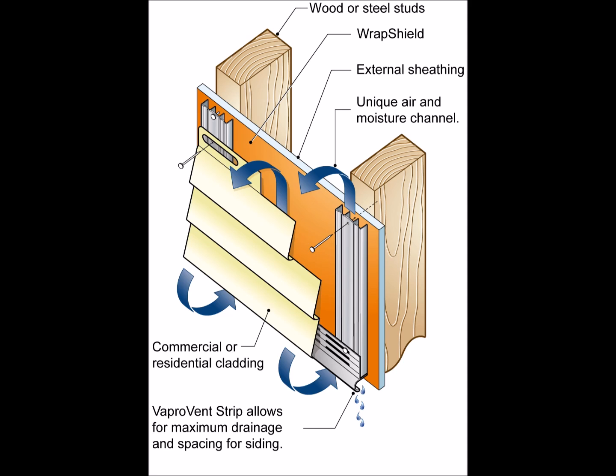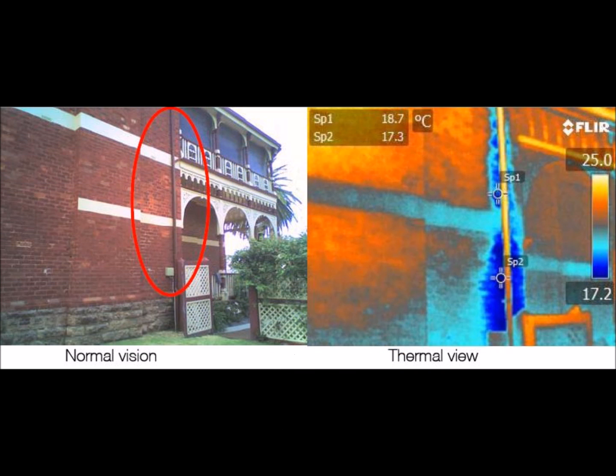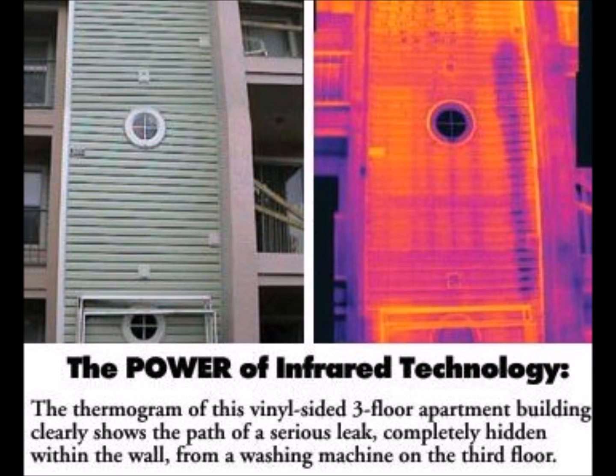You should know that if you're using a thermal imaging camera and there's spalling taking place, there could be a temperature difference in that area. It is most likely that the spalling area is retaining moisture. It is not warm air coming through the brick. If you ever question whether something's wet or not, it's always best to use another tool like your moisture meter in order to determine whether it really is wet.